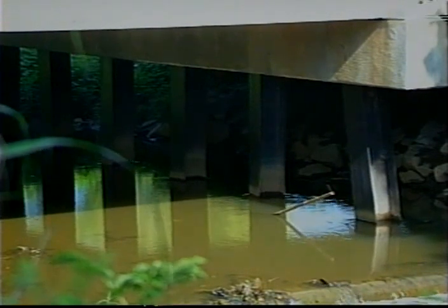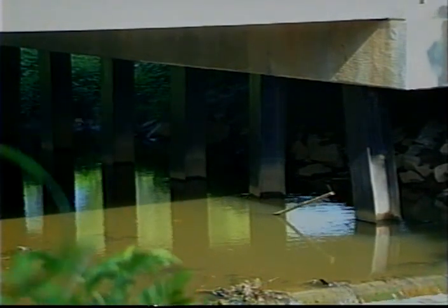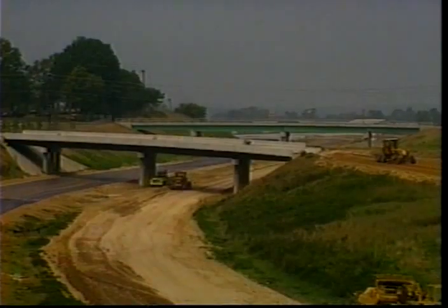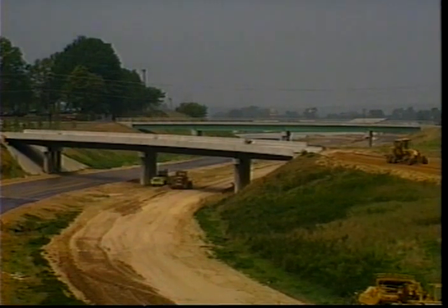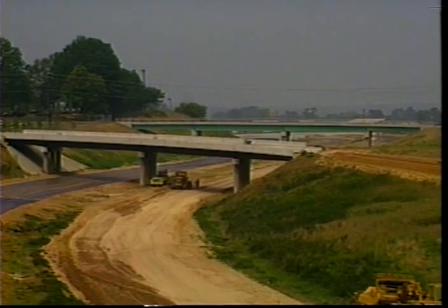Piles are linear foundation elements that are driven into the earth to carry loads through weak soil layers to stronger layers. Other foundation elements include footings and drilled or excavated piers. These basic components are constructed in many different configurations and materials, such as concrete, steel, timber, and composites, to provide economical design solutions in different situations.